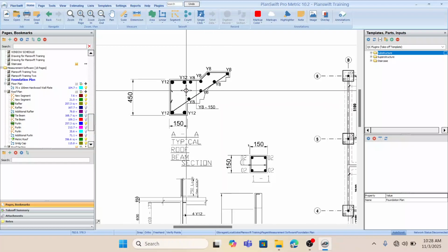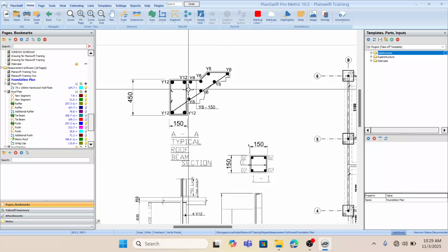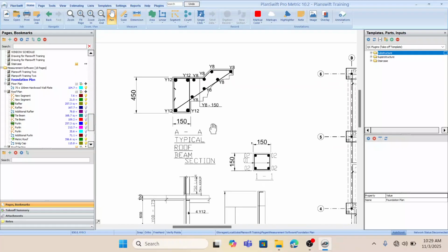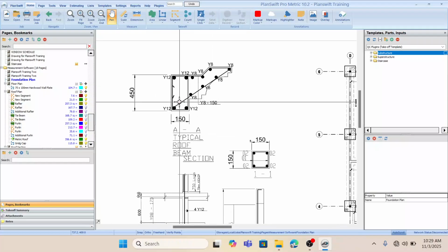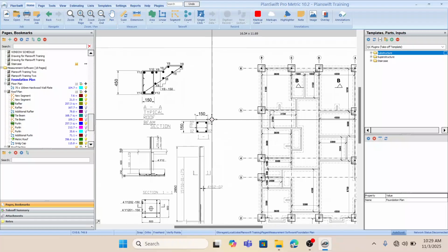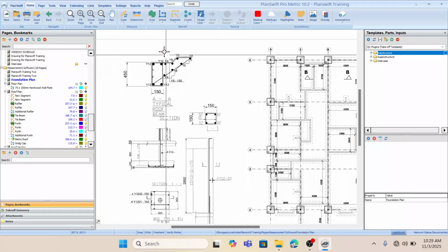You see, some concrete fascia will be flat, more or less like flat concrete extending beyond the wall, and maybe with a little design like a step. So let's quickly measure our concrete fascia. The first thing we're going to measure here is the concrete, because we all know concrete is measured in meter cube. So I'm going to measure this concrete with the aid of our area tool.